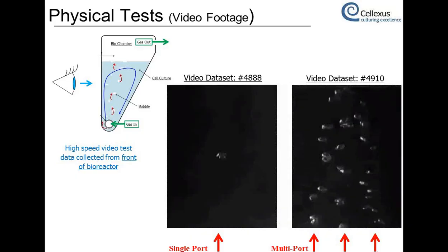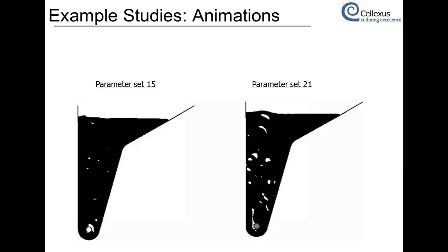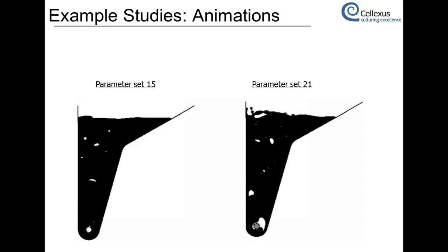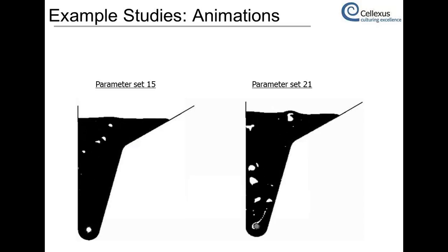And here it just represents a graph of 3 different types of data sets from different studies we did in terms of flow rates, height of the column, positions of the holes, and locations of the holes. And you can see there's quite a diverse data set there in terms of equivalent circular diameter. Now the idea was to then model these and ensure that our CFD model was validated. So what we ended up doing is doing a number of runs with those particular data sets and ensure that our models were in line with what was coming out of the physical tests.